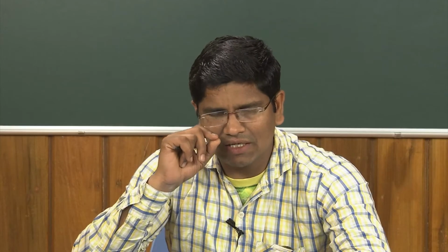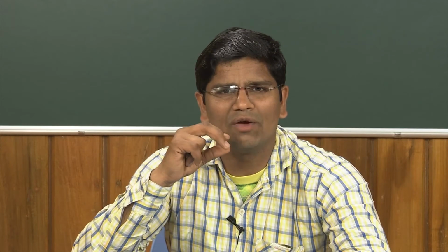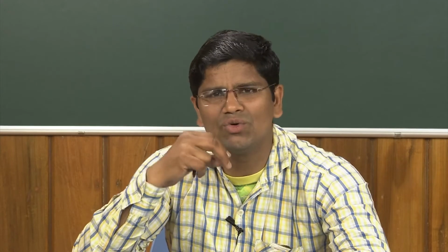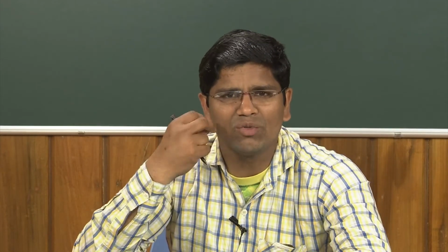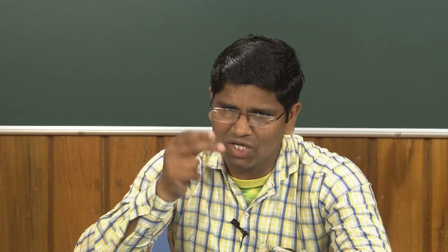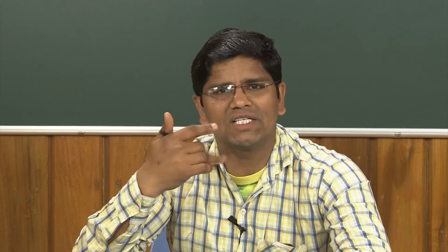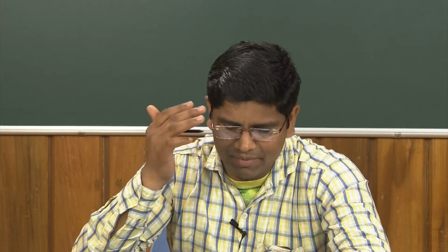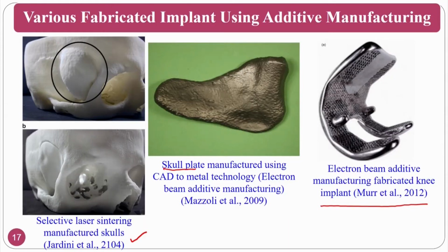but the only thing you have to see is that 3D printing doesn't give you a very good surface. In those circumstances, you need to go again for micro machining applications and polishing applications also. That's why people nowadays are working on surface roughness in 3D metallic as well as ceramic components. That's why here also conventional machining or slightly advanced machining, that is micro milling and all those micro machining processes, play a major role even though you are developing 3D components.